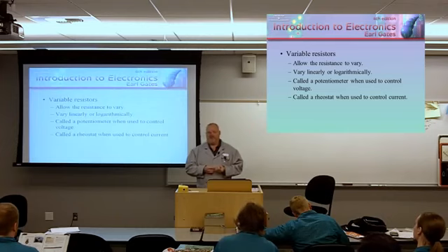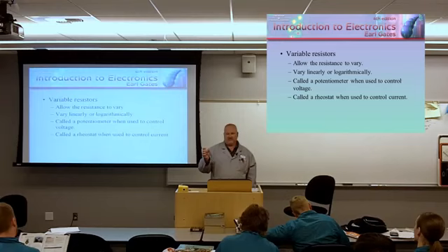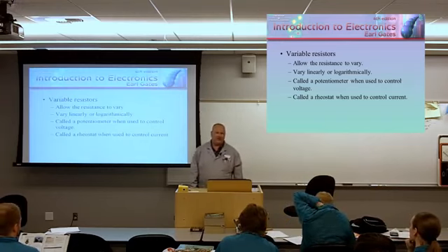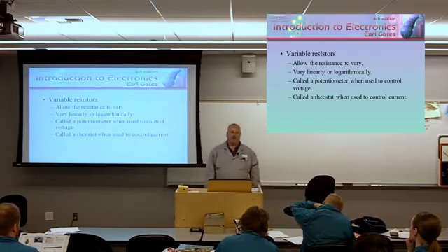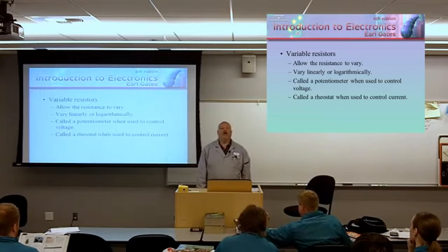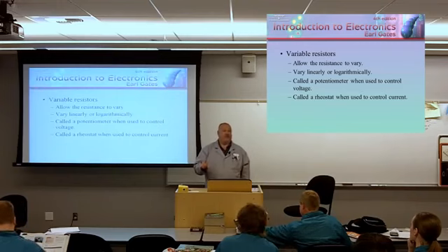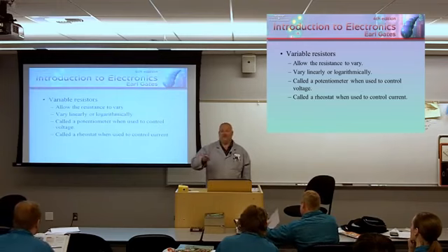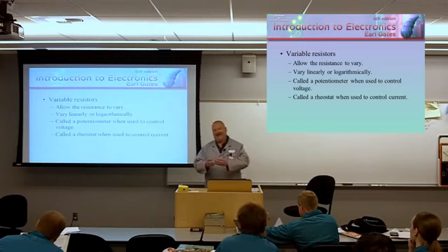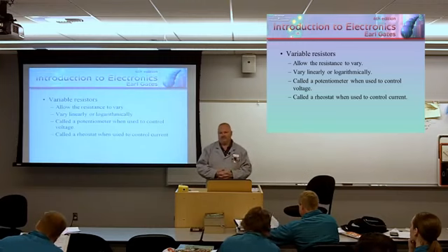If you're shopping for these variable resistors, you may also see it say audio on the box because it's for use with audio. So a volume control on a radio or a stereo would be a logarithmic control because it's controlling something that is nonlinear. What we're trying to do is get somewhat of a linear response out of it, right? When you turn the volume all the way up to 100%, you expect to get 100%. When you turn to 50%, you expect to get 50%. But since audio is nonlinear, we need to use a logarithmic control to get a linear type response. Make sense?